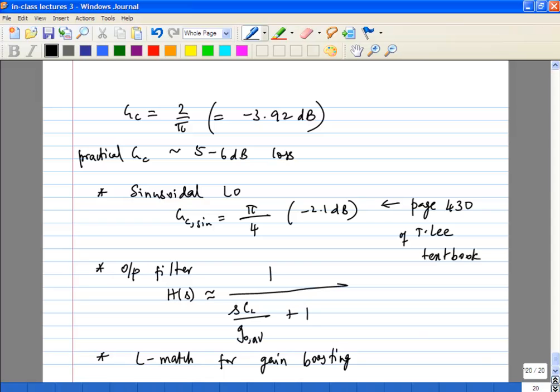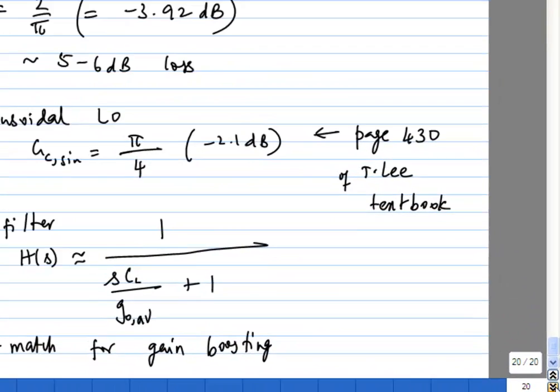Okay. So if you look at the noise figure of this guy, the noise figure will be maybe 10 or 11 dB, which is still pretty good for the loss you're getting. Still pretty good. IIP3 can be pretty decent. It can be around plus 10 dBm, sometimes higher.